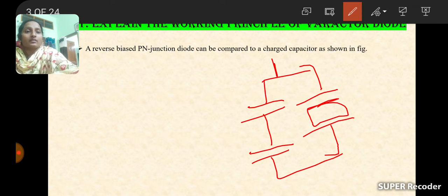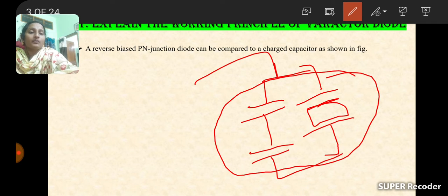But in the Colpitts oscillator, the frequency is determined with the help of all tank circuit elements, inductor, capacitor 1 and capacitor 2. Here the frequency depends only on the crystal. That's why it is also called the frequency determining network in the crystal oscillator.